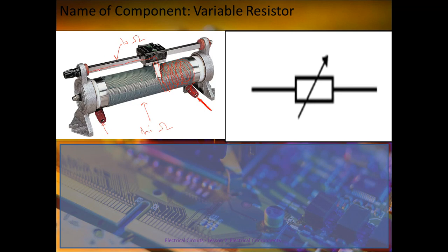So you'd get about 2/3 of the journey in low resistance, and then 1/3 of the journey would be in really high resistance. If we were to move that slider to the left and position it around here, that would give a much higher resistance journey, because now we've got much less bar to go through, and very early on in the journey the electrons drop down into the high resistance coil, and they've got to go all the way around that coil before they can come out in the bottom right corner. So that's how we would alter it.